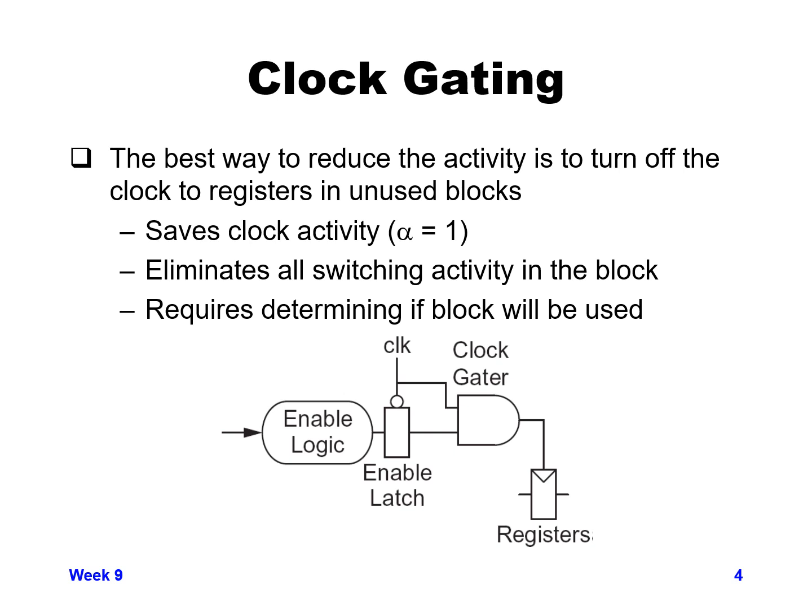So below here it shows an example of that, where instead of just having a clock come in and go through a number of buffers and go to all of our registers, our flip-flops or latches, we can send the clock into an AND gate and have an enable logic that gets latched just before that AND gate. So we send an enable in. If the enable goes low, then that enable is ANDed with the clock,